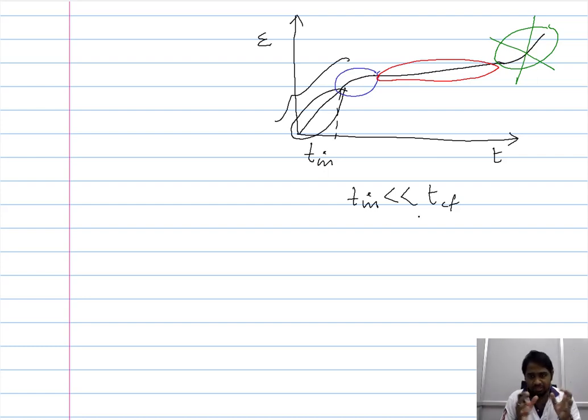So when you consider exclusively the time spent by the material in different stages, the instantaneous creep doesn't contribute to the overall life of the material. And more or less the same goes for the time spent in the transient creep, because transient creep just relays the instantaneous creep to the steady state creep. So the time spent even under the transient creep is not of the same order as the time spent under the steady state creep.